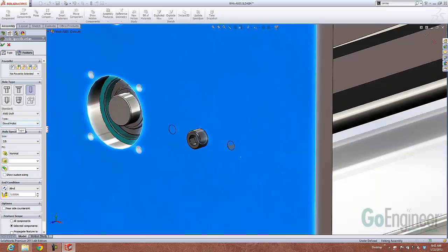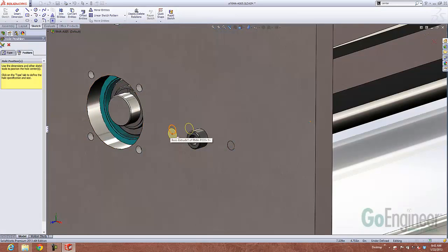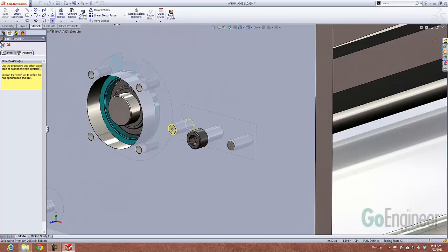By selecting dowel holes and selecting the size, we'll say maybe 7/16. You can specify, make them a clearance, and you can specify your dimensional tolerances, so we can say this is a D or an H. But what this allows me to do is go ahead and just use my SOLIDWORKS geometry in the assembly to place my dowel holes. We'll just reference those. We'll place them right here, so the dowel holes will go right where the shafts are.